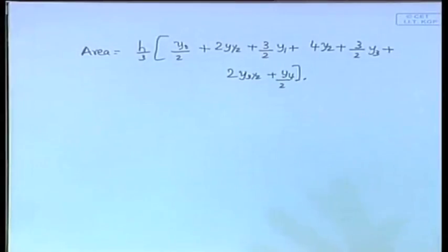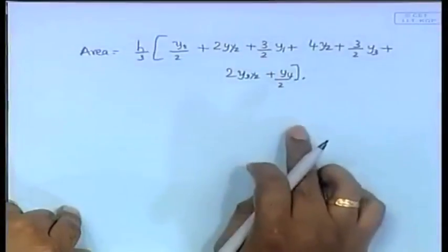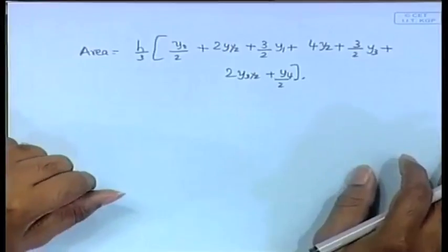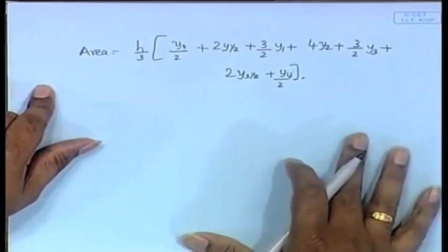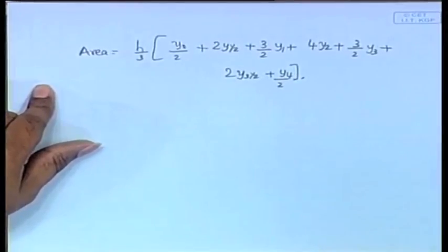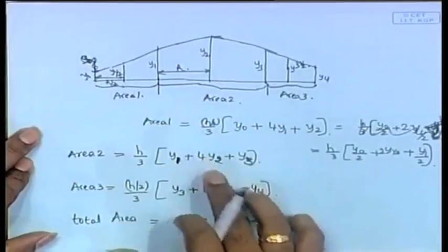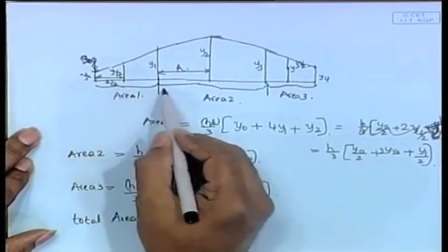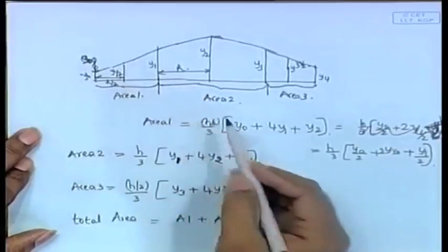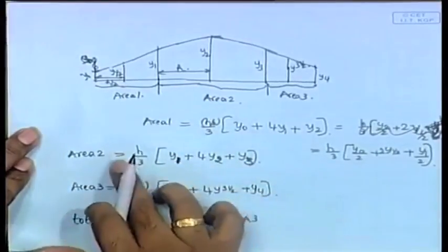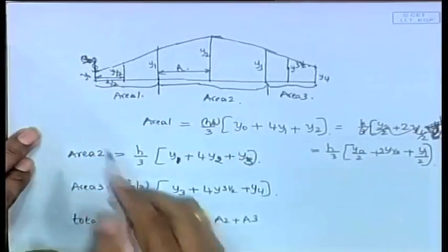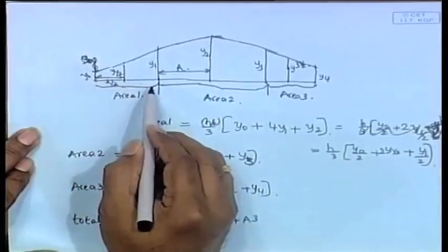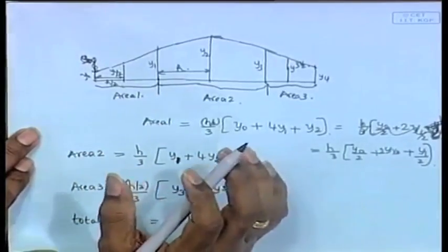So, you cannot really predict your answer in this case. Of course, you can memorize this, but you won't have the same number of ordinates. So, you do not memorize any of this, that is not the goal. Your idea is just to do this summation. The only thing to remember is this is h by 2 and this is h. Because you are doing Simpson's first rule, always take 3 ordinates and divide it, then you won't make any mistake.